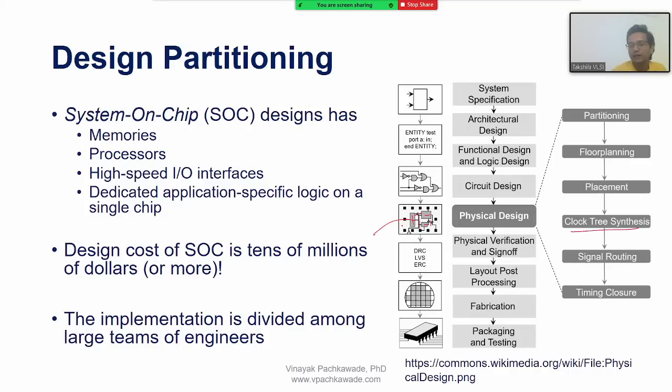Obviously the functional and logic blocks that you have placed are called combinational blocks and sequential blocks. I have told you what they are. Sequential blocks are flip-flops and latches, which have a clock, because their output depends not only on the present state but also on the previous states. We have seen that. So when there are sequential blocks, there comes a clock. And then signal routing.